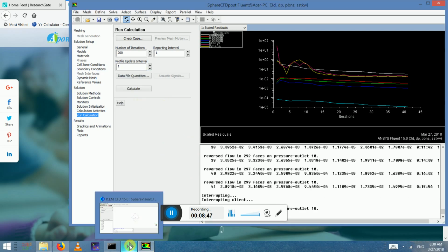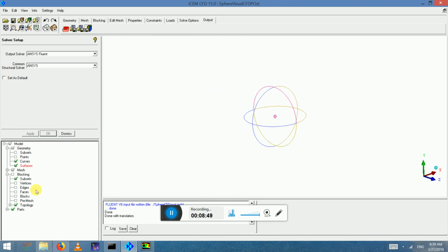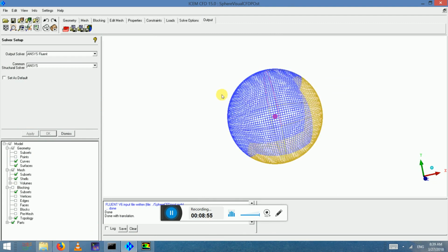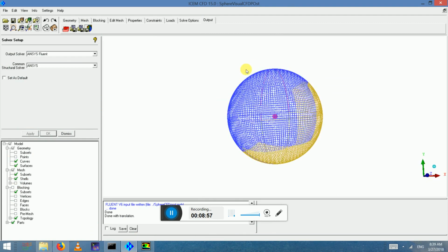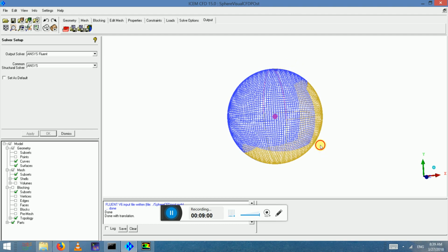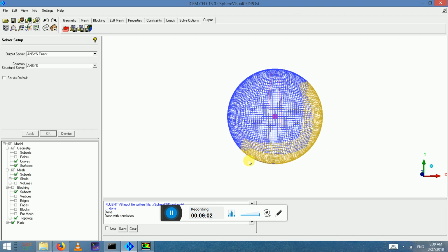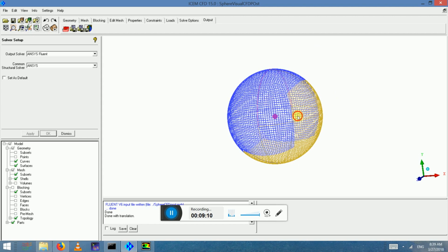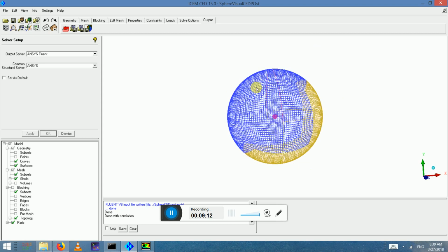So it is because we have the outlet. If I show you, the outlet is not appropriate. Basically the outlet has to be all this side in X direction, but I have some outlets here as well, because I did the mesh a bit quick. The outlet's supposed to be far behind, not underneath. Anyways, it's not going to be a big problem for our visualization purposes.